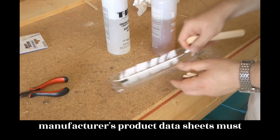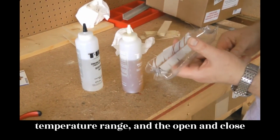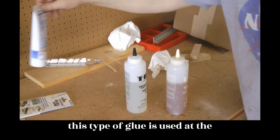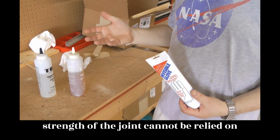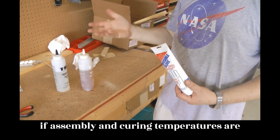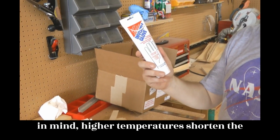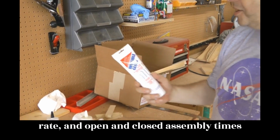The manufacturer's product data sheets must be followed regarding mixing, usable temperature range, and the open and closed assembly times. It is very important that this type of glue is used at the recommended temperatures, because the full strength of the joint cannot be relied on if assembly and curing temperatures are below 70 degrees Fahrenheit. With that in mind, higher temperatures shorten the working life because of a faster cure rate, and open and closed assembly times must be shortened.